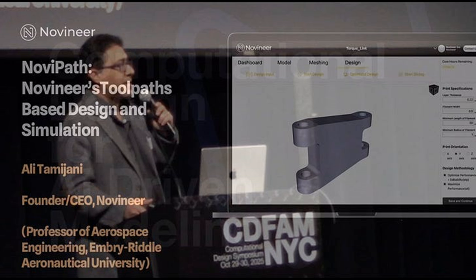Right? And sometimes there is a discussion whether I should do a stiffness-based or a strength-based optimization. Strength-based is, of course, much more difficult, but much more valuable. Here is an example. So this one is stiffness-based, that one is strength-based. You see while the stiffness in both designs is kind of similar, 103, 96, the failure load is completely different, right? 42 versus 96. So 2 times better failure load if you do strength-based optimization.